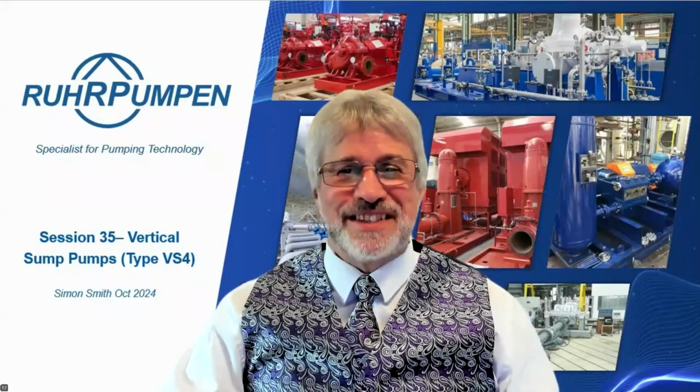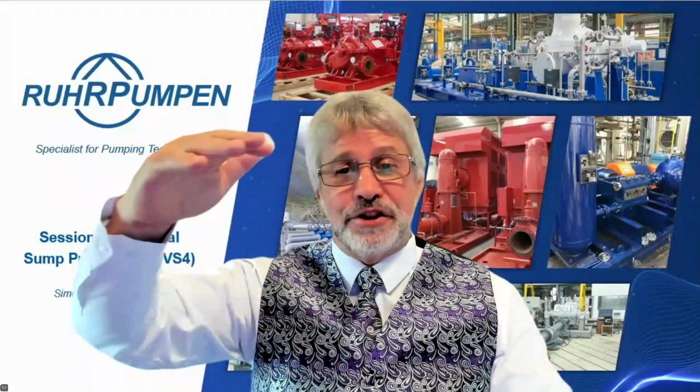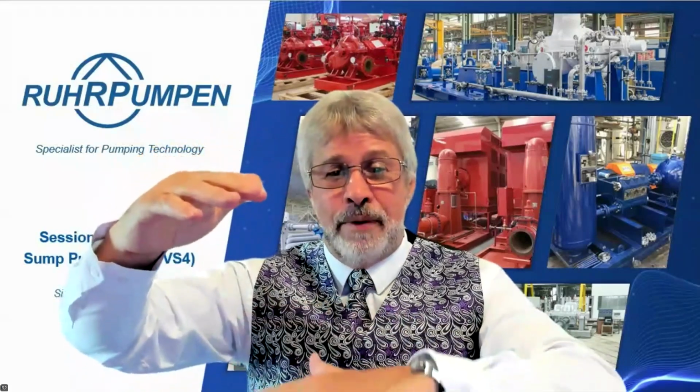Simin Moshki says, you know that in a mechanical datasheet, differential head has been considered from the discharge flange. How much head should be added to that? Yep, you're quite right. It's a common thing on many vertical pumps that people forget to take into account the elevation from the impeller to the discharge flange.